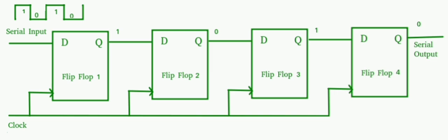Analog to digital converter. Specification of ADC: voltage range = Vmax − Vmin, resolution = Vrange/(2^n − 1), which is 1/(2^n − 1) × 100 in percentage. Dynamic range = 1.8 + 6n dB. Types of ADCs are counter type, dual slope type, successive approximation register type, and flash type.